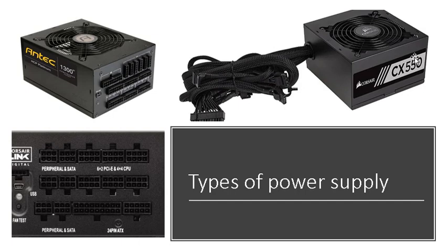you want to avoid a non-modular power supply. But if you're thinking about just getting a power supply, connecting it to your computer and never touching it again, then this might be a very good choice. And another reason that you want to avoid this is that in case one of these cables, for example, gets cut off or fails for some reason, you're not able to replace it, so you need to replace the whole power supply, which is not very good. It's going to be a bit of a waste of money.